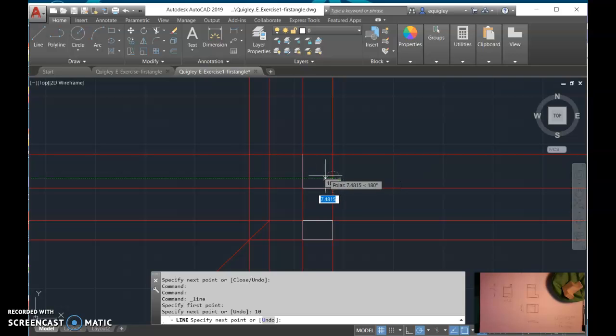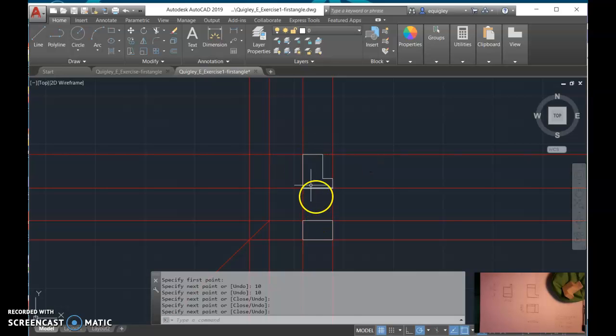And then it comes across by a distance of 10, so we can key in that distance 10 while we're dragging horizontally and press enter, and we have the 10 across. And then it goes all the way up to the top. So it's offering us an intersection there with an object tracking vertical green dotted temporary construction line from the previous point, and then across the top to close. So those are the lines that outline the top view, the front view and the top view.